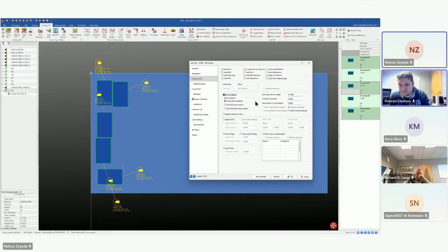For most lasers, at least, they have a safety height and then their regular height. So it'll swap between those as it's moving across the sheet to, again, reduce the chance of any kind of collision happening. If there's a tip up for whatever reason, the machine should at least be at its safety height, based on your parameters in here.